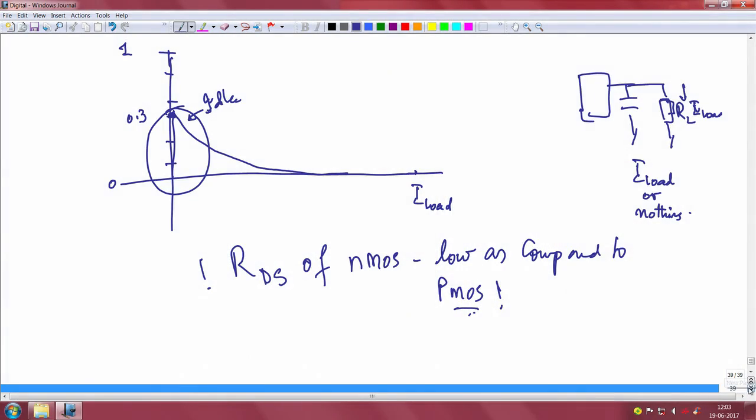How the charge pump circuit functions, we will worry about separately, but that is what will be required in the NMOS case. But in the PMOS case you do not have to worry about it, because simply getting down the gate voltage or increasing the gate voltage will ensure that the conductance of the series pass element is taken care of. So let us quickly put down that circuit and explain a few things so that that part of the study on LDO is also completed. So let us start with that.